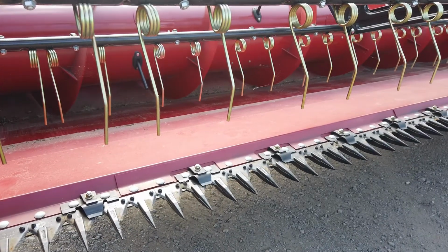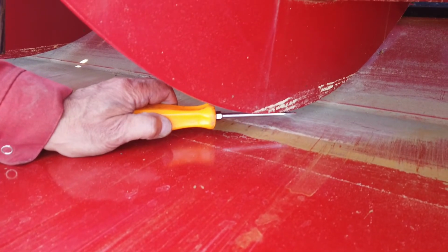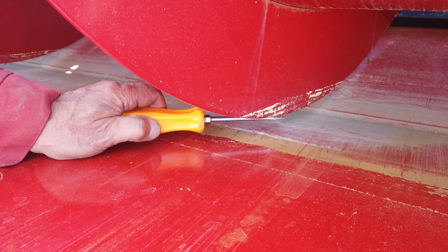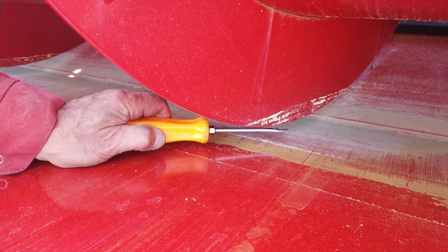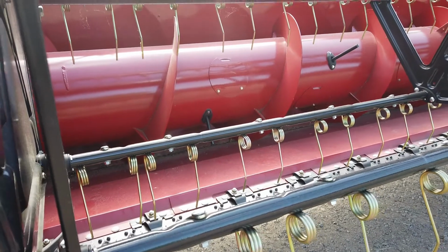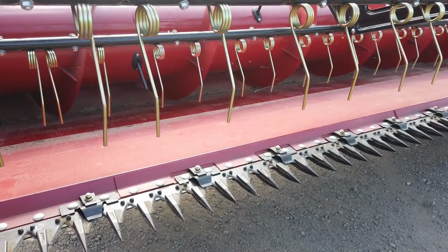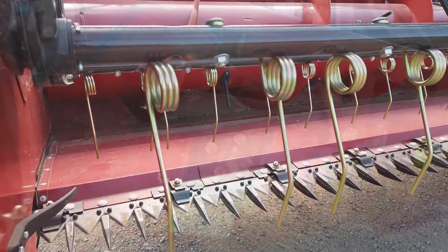If you experience frequent blocking of the auger, then the chances are that the auger needs height setting. Set the flight to bed clearance to suit the bulk of material to be fed to the centre. For example, for rape, set it at approximately 25 mm, wheat 15 mm and barley 12 mm. Take account of where the knife is likely to be positioned so as the flight and tines do not interfere with the knife bed slider skin when fully in.